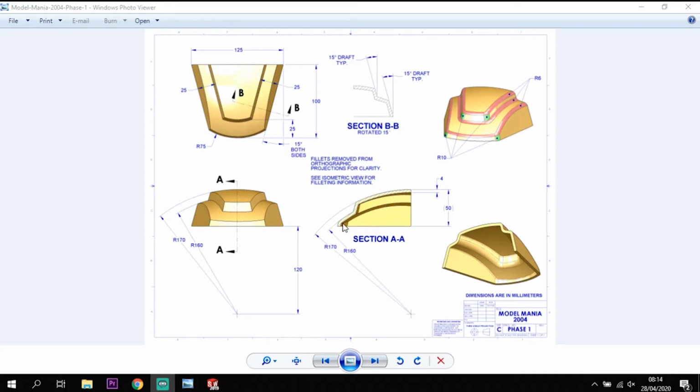Then once we've got them radiuses in there, I will look at adding in some draft angles on the shapes here to get it up to where I want it to be. With them draft angles on, I can then add in the fillets and shell this section to leave me with the finished component. So let's dive into this and have a go.